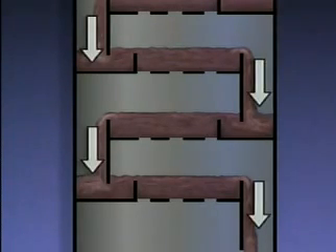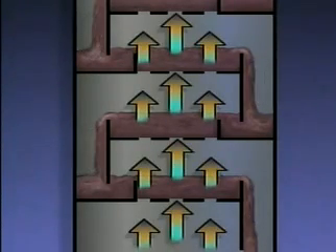The openings in the trays allow vapors to rise through the trays on their way up the tower. Each tray is also designed to hold liquid. Dams or weirs on each tray allow liquid to build up on the tray. Liquid that overflows the weirs flows into downcomers. The downcomers channel the liquid from tray to tray down the tower. When the upward moving vapors and the downward flowing liquid come in contact on each tray, the vapors transfer some of their heat to the liquid.